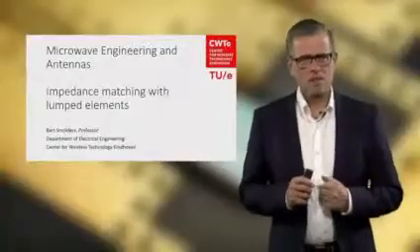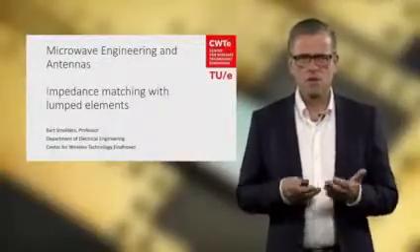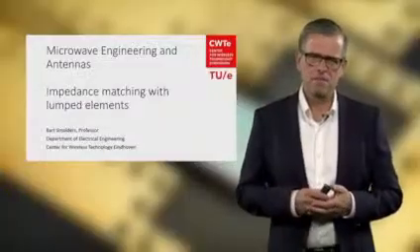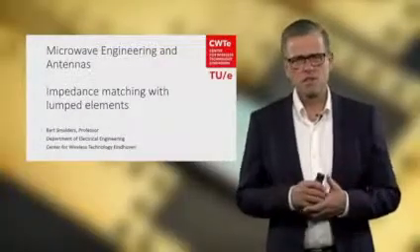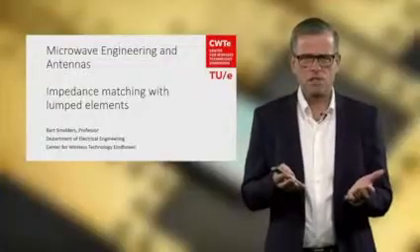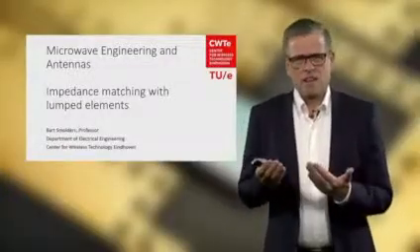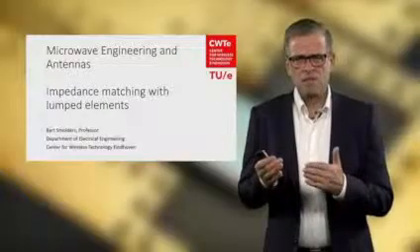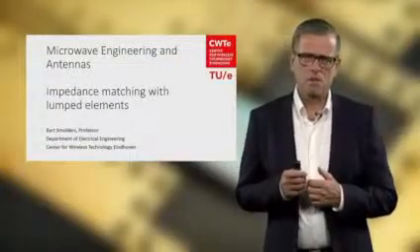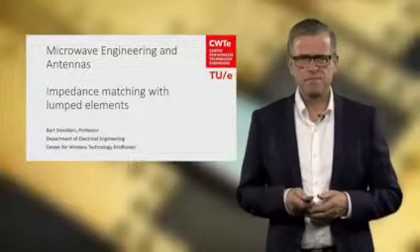Welcome to this web lecture. We're going to talk about impedance matching, and in particular we're going to use lumped elements to perform this matching. Many applications require matching circuits. For example, a power amplifier which is connected to an antenna might not have the optimal impedance matching in between. So you could correct that by adding a matching circuit.